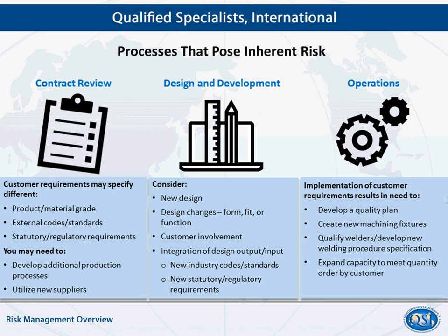Another question, depending on what industry you're in: you may have to create new machining fixtures that may need to be approved by your customers. If you have a fixture department or a maintenance department that makes your fixtures, you may want to have a quality hold point on that fixture to make sure it's the appropriate fixture for the appropriate job.